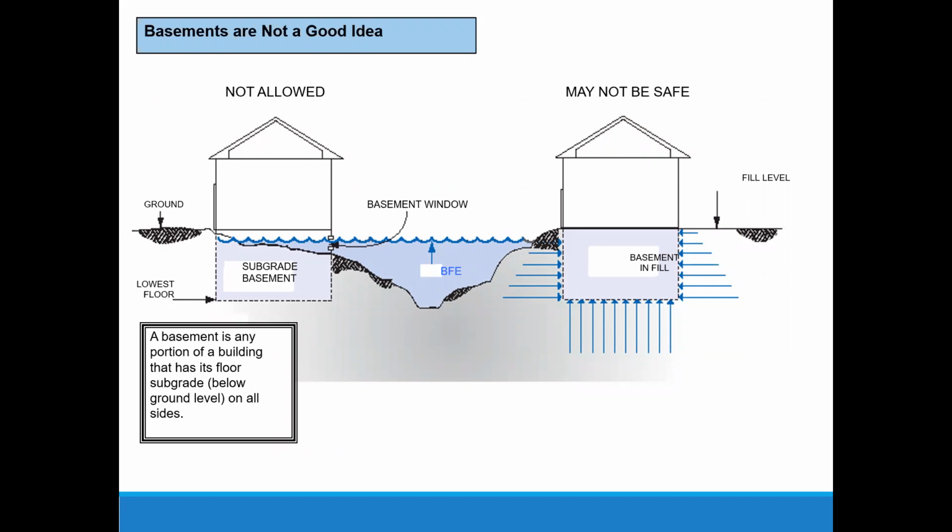So you have floodwater infiltrating the soil. As you go down into the soil, that pressure increases linearly with the depth, and so it increases the pressure that's being exerted on the structure. And of course, if you have a basement in there, you just have empty air on the other side. And so that pressure can cause walls to crack. It can burst through the floor with the buoyancy that's being exerted on the bottom of the basement floor, and so it can lift out of the ground.